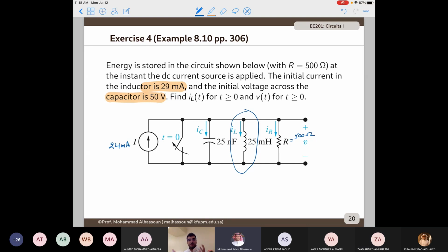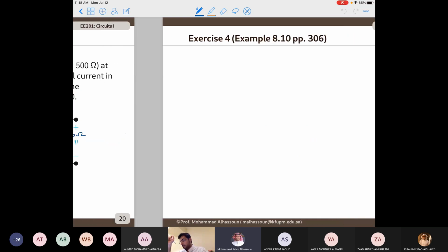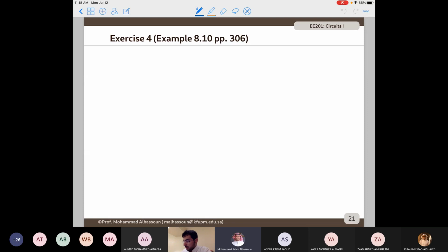with chapter 8, with the parallel RLC circuit, we have 3 options. So we're not going to invent anything new. Either we have an overdamped, critically damped, or underdamped response. So we need first to know which response we have. If we know which response we have, we know the form of the solution. From the form of the solution, we can go and look for the missing information. Is that clear, guys? Yes. Okay, very good. So we need to verify.